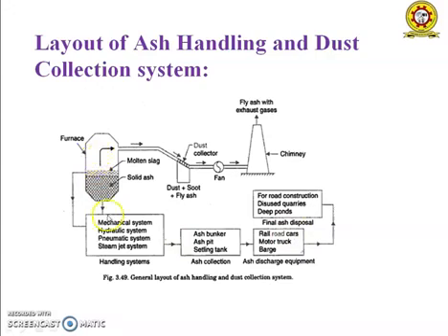The solid ash can be removed by mechanical, hydraulic, pneumatic and steam jet systems. From this, the ash is collected in an ash bunker, ash pits or settling tank. This ash can be transported using railroad cars, motor trucks and garbage, and from there it is used for recycling in road construction, disused quarries, deep ponds and brick manufacturing. This is the final disposal method.